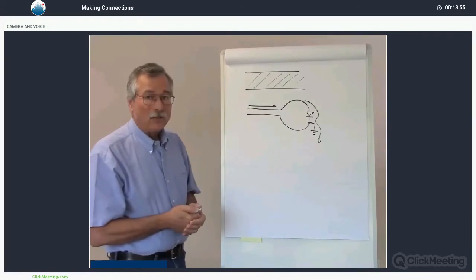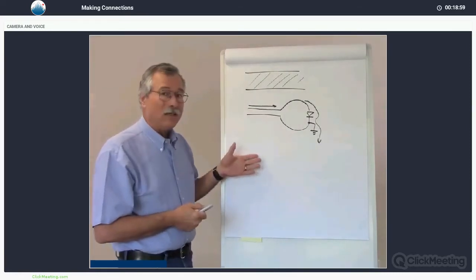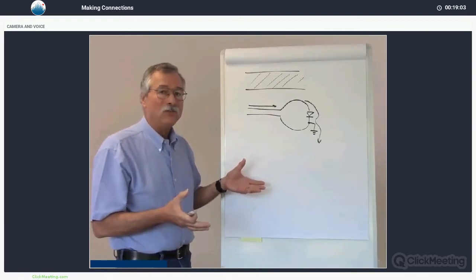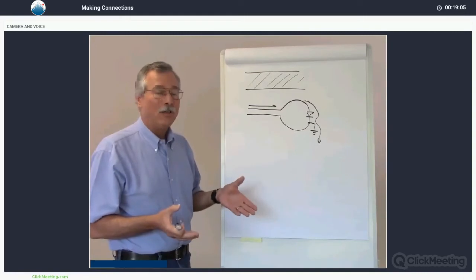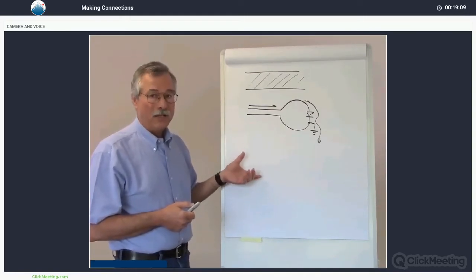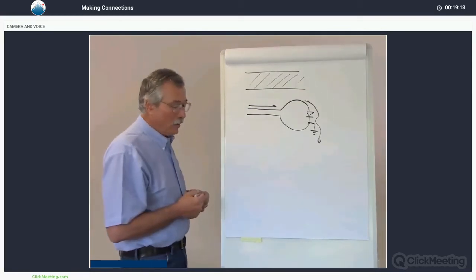Some folks may be inclined to use other types of cables, twisted pairs, and so on. You can do that if the rise time is not so fast. We have products that use twisted pair as the output cable, but those rise times are in microseconds and not nanoseconds. Big difference, factor of 1,000 there.